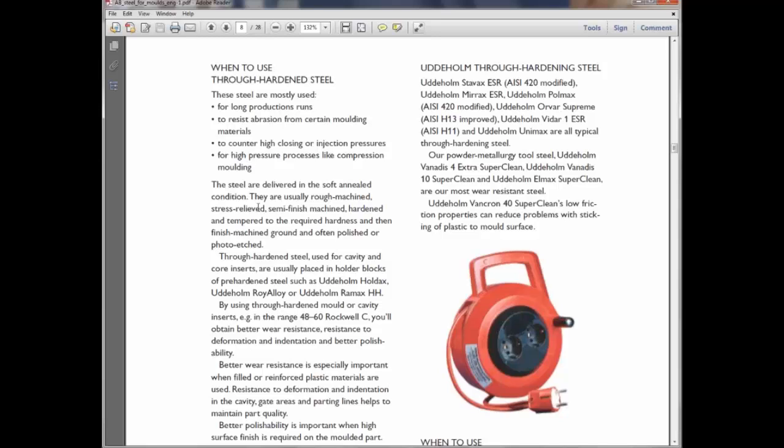Then we bring the rough machined component again and go for small cuts. After that we go for semi finishing, and then finishing of the material. In semi finishing we hardly give 0.1 to 0.2 depth of cut. So at that time residual stresses don't get created.